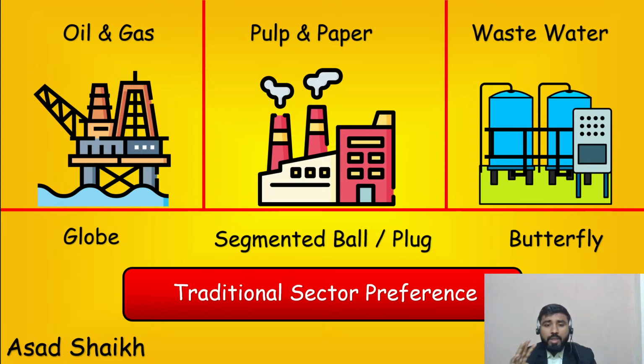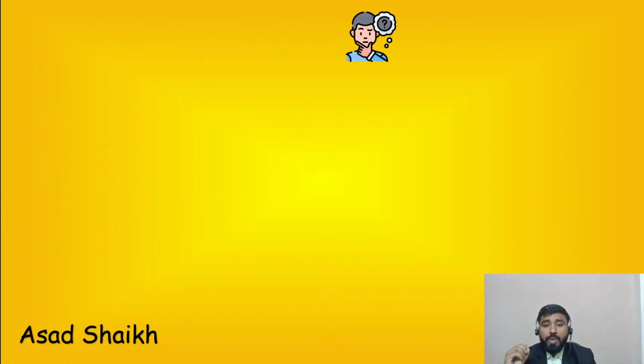So what we learned was four important things. First is the budget, which highly depends on the size of the valve. Then it depends on which type of application you have, for example high differential pressures, or do you have cavitation and flashing issues happening. And finally you would also have to see how precise your flow control is required to be. So we'll make a quick summary.